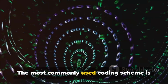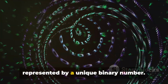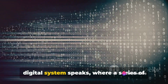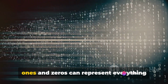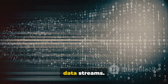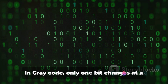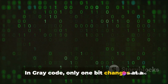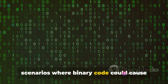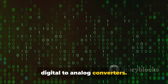The most commonly used coding scheme is binary coding, where each output state is represented by a unique binary number. Think of it as the language that our digital system speaks, where a series of ones and zeros can represent everything from a simple on-off signal to complex data streams. Another popular coding scheme is gray code. In gray code, only one bit changes at a time, making it particularly useful in scenarios where binary code could cause errors, such as in analog to digital or digital to analog converters.